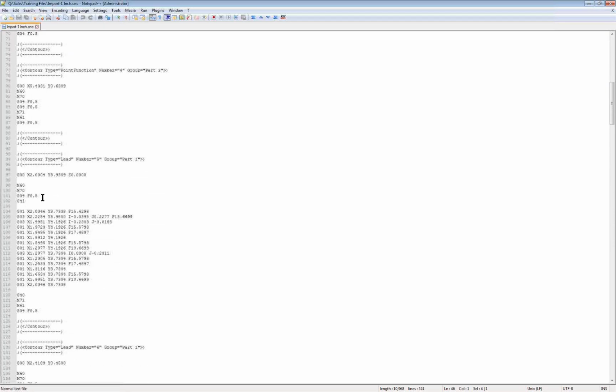And then when we get to actually cutting those slots, similar type thing, turn the water and the abrasive on. We have this G41, which is a tool offset command. We are offsetting for the diameter of our tool. If you want to add additional tool offset at our controller, that's why this G41 is in here. So as the nozzle starts to wear, at our controller you can add additional tool offset, and this G41 tells the controller which side of these lines to add that additional tool offset to.